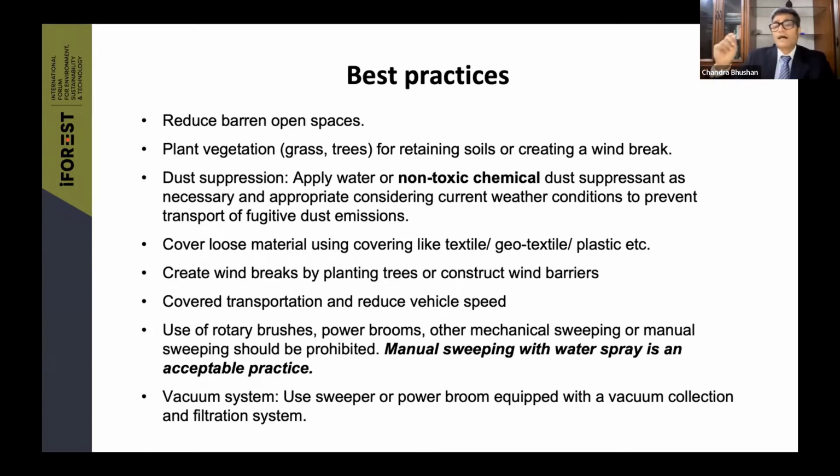As far as transportation is concerned, if it is a loose material transportation, it has to be a covered transportation, and the vehicle speed has to be reduced. So vehicle speed is not only important, less vehicle speed within a city is not only important from accident prevention, it is also important from dust prevention. Speed determines how much material will be mobilized in the air. So if a truck is transporting loose material, it has to be covered and it has to move at a low speed. It cannot move at a very high speed.